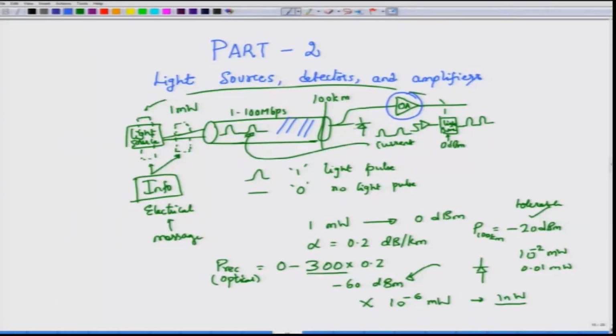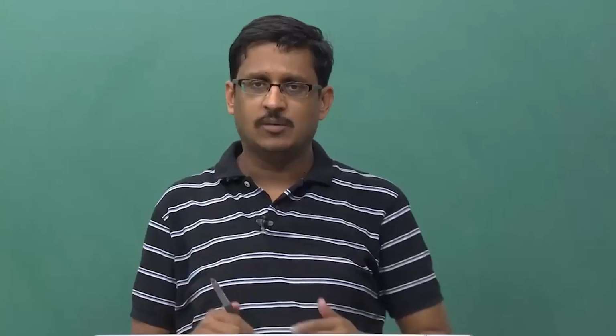So, this conversion from optical to electrical domain is sometimes characterized as O/E, standing for optical to electrical conversion, and then converting from current or electrical format onto the optical is called E/O, which is electrical to optical conversion. So, before the discovery of optical amplifiers, it was this method wherein at the end of one span you take the optical signal, convert that into electrical format, amplify it, reshape it, do all of that, and then convert from electrical to optical signal back.